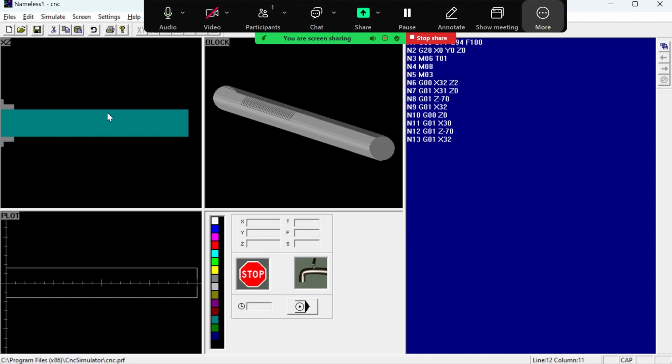And again, when we are lifting the tool from this point to this point without changing the z coordinate, the tool will again be in contact with the workpiece. So we just write g01 here, so that it does not move rapidly to this point. Once the tool has reached here, we want the tool to move from this location back to this location. So we'll just use g00, which is rapid repositioning, because the tool is not in contact with the workpiece anymore, as we have lifted the tool up. So we will mention z0 without changing the x coordinate.